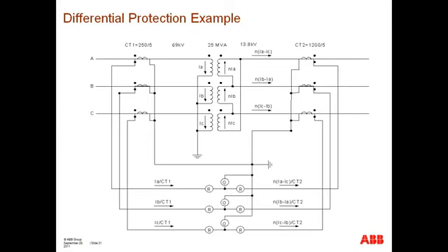So I'm going to assume that what the question is, is that when monitoring a transformer that has no phase shift at all from one winding onto the other winding, you should expect a 180 degree relationship between the high side currents versus the low side currents, and this is because of the way the CT polarities are installed. Okay, and I'll explain that in just one second with the slide that you have in front of you.